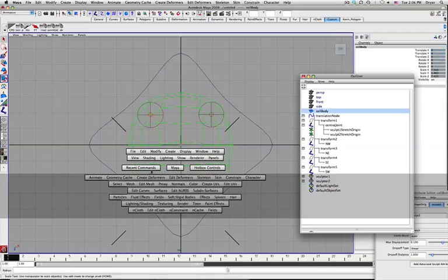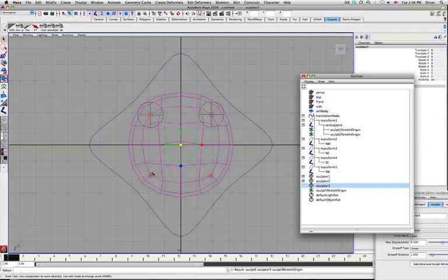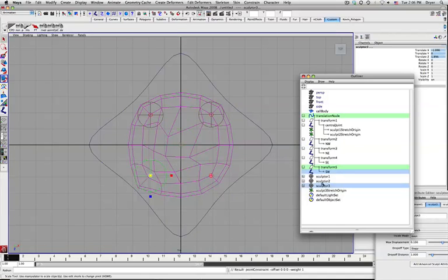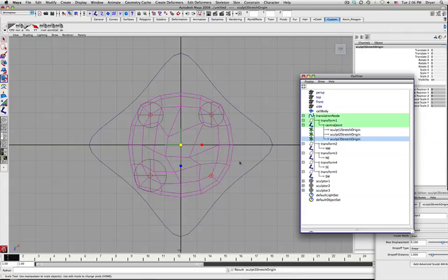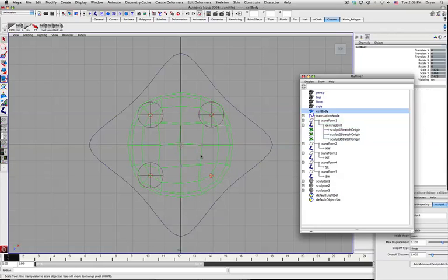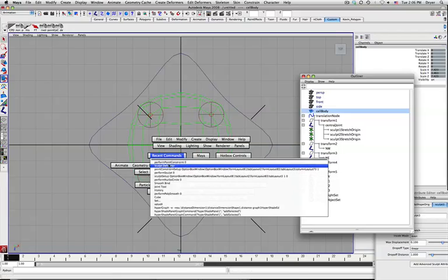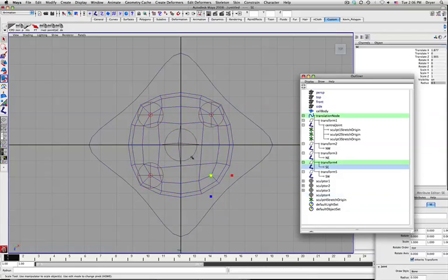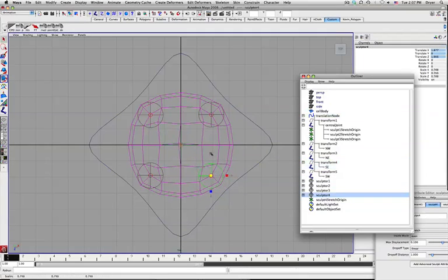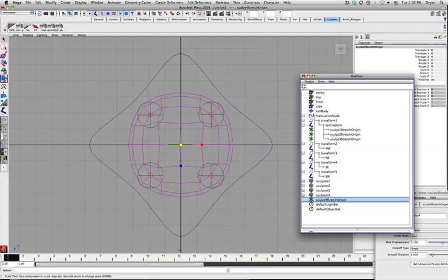Select this sculpt deformer, joint, sculpt deformer, perform point constraint, scale it down a bit. I'm working at a different scale this time. Again, just select the geometry, sculpt deformer, joint, sculpt deformer, recent commands, perform point constraint, scale this down a little bit. Okay, I just have to now parent this last sculpt stretch origin locator to the central joint.